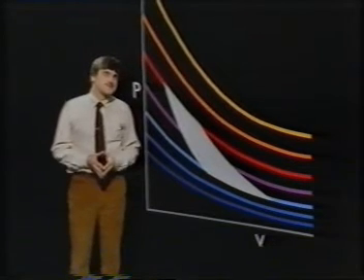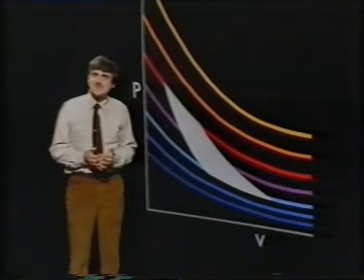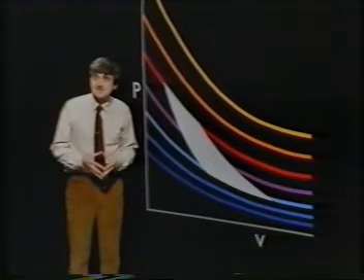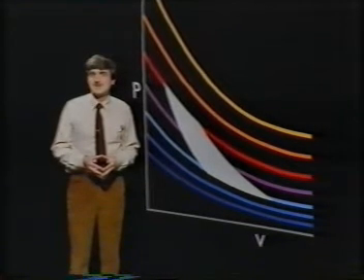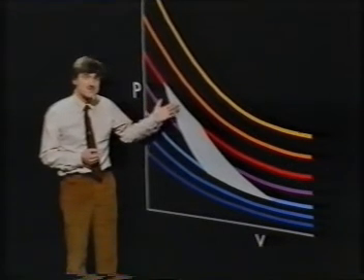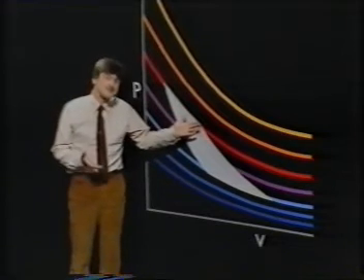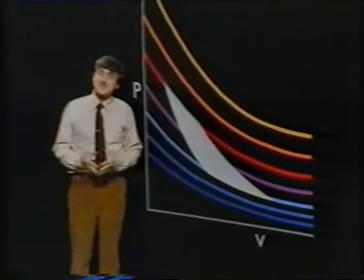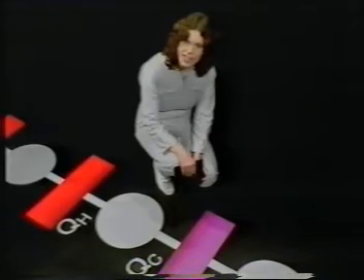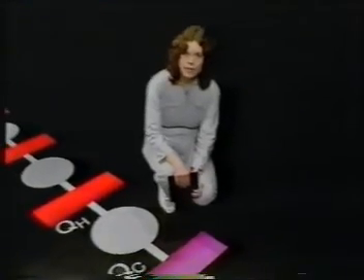Just one final point. The rate at which that heat transfer occurs does depend on there being a temperature difference. The larger the temperature difference, the faster the heat transfer will occur. Now, in a purely theoretical Carnot cycle with zero temperature difference, you can imagine that this heat transfer process will take forever. Now you can see why the Carnot cycle is a purely conceptual model. But nonetheless, the Carnot cycle can lead us to ideas that we couldn't get in any other way.